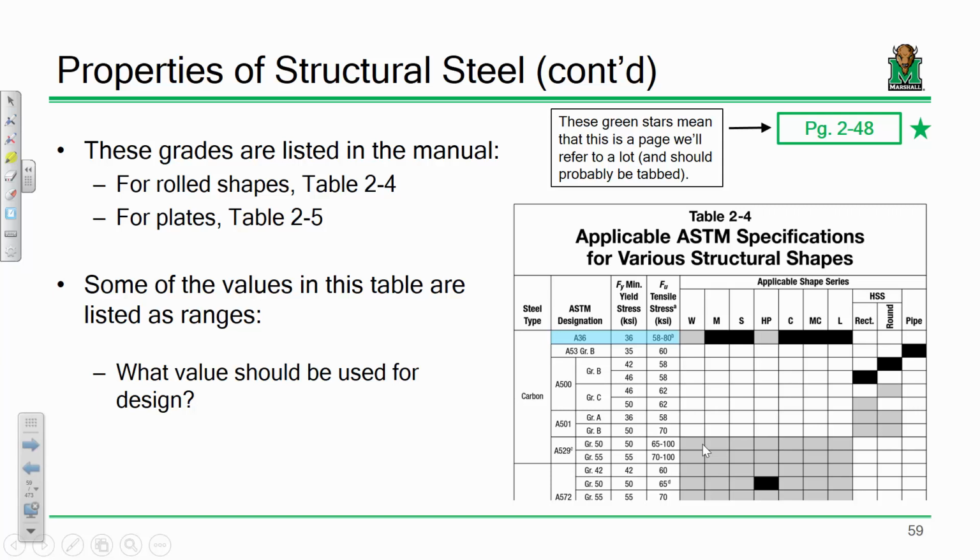In 1994, the Northridge earthquake happened, and there were a lot of structural steel frames that the community thought would be fine, and after investigation, they found they cracked and fractured all over the place because they weren't as ductile as we thought they were. So that's why those ranges are reported. Just food for thought. But in design mode, when you're designing tension members and connections and things like that, use the lower value. That make sense? Okay, that's important because that will come up.